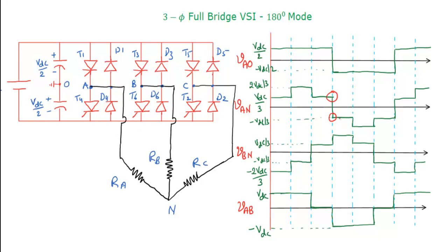If we turn on the thyristor T4, we get negative voltage. Like that, phase B also: here we complete the conduction by thyristor T6 and turn on thyristor T3. After 180 degrees, T3 will be turned off again and T6 will be turned on. That will happen on every phase, for every 180 degrees of conduction of the respective thyristors on that particular leg.